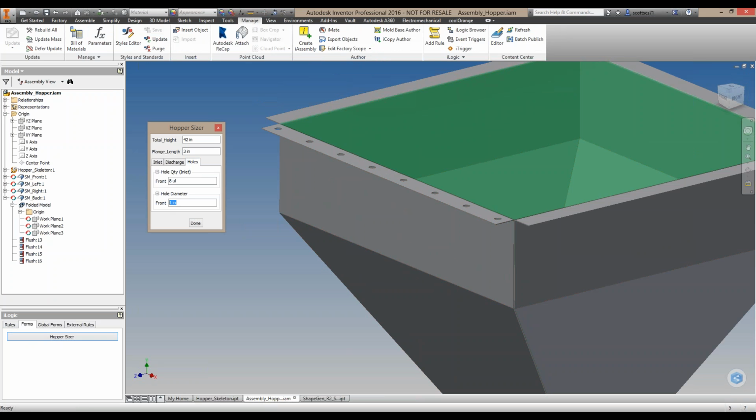I don't need a 1-inch hole. I need a 1/2 inch hole. So by linking that back into the part through iLogic, I'm allowing one location, the top level of the assembly, to drive the holes, the size of the sheet metal, and the bend radiuses, or the bend angle, and all that is defined by the assembly itself.